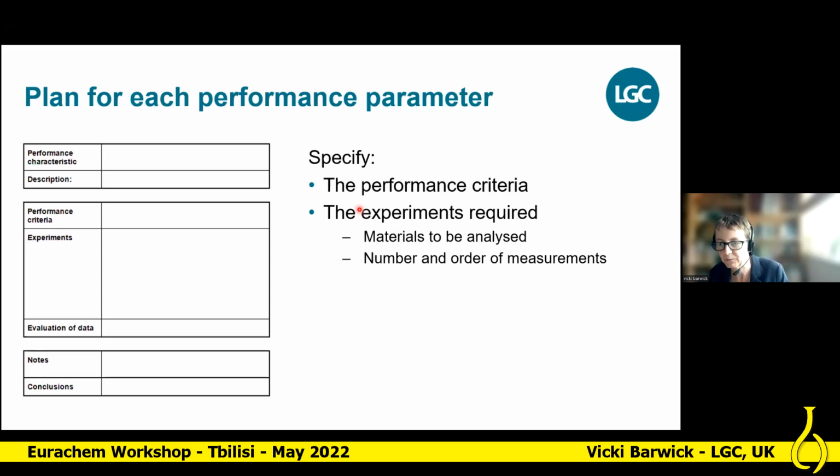suitable number of measurements. So for example, to get a reasonable estimate of a standard deviation, which might be then used to express precision, then somewhere maybe between around 6 and 15 measurements might be considered suitable. Of course, there's always that element of balancing what's practical and sort of how reliable our estimates need to be. But we need to make sure we've got sufficient data to give us a reasonable estimate of the method performance.